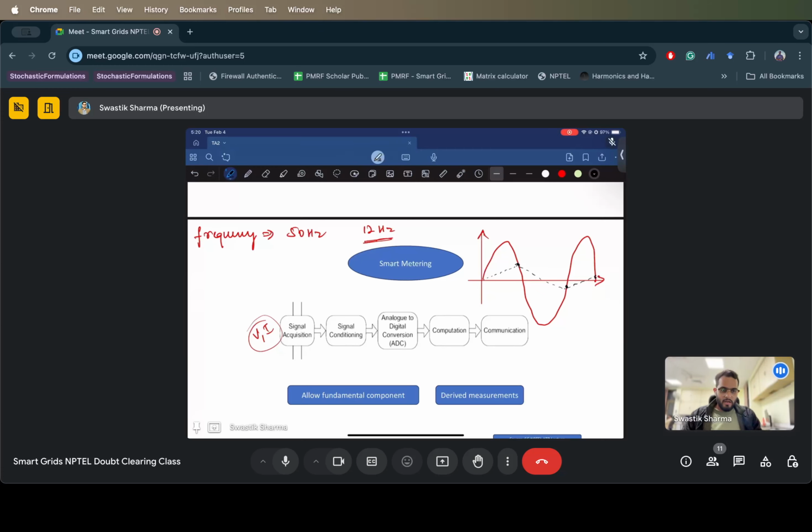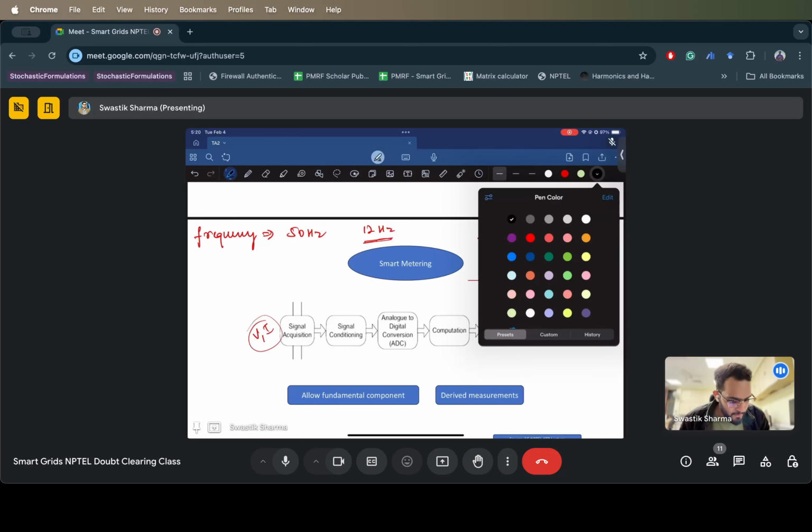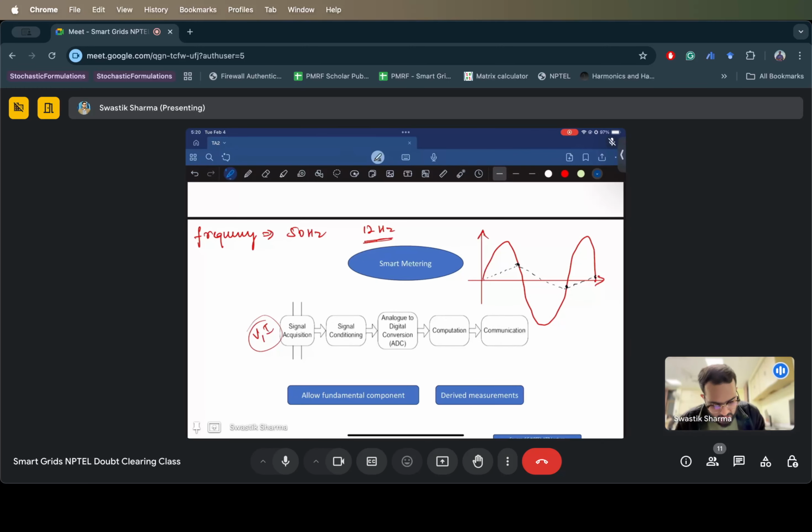So this is not how my signal is supposed to behave. You should sample it at more than its fundamental frequency, right? So if we sample it at a much larger pace, let's say 26 hertz or 30 hertz, I sample it here, then again here, here, here, here, and here. So now the quality of my signal would be something like this.